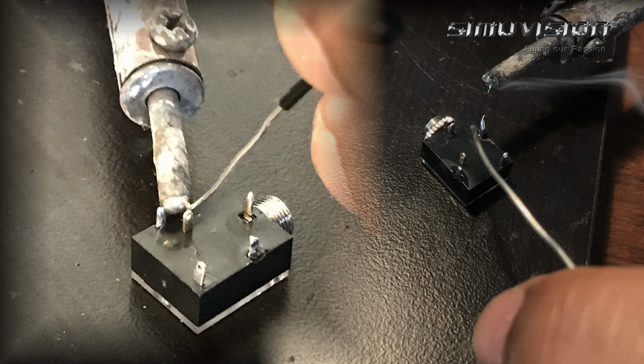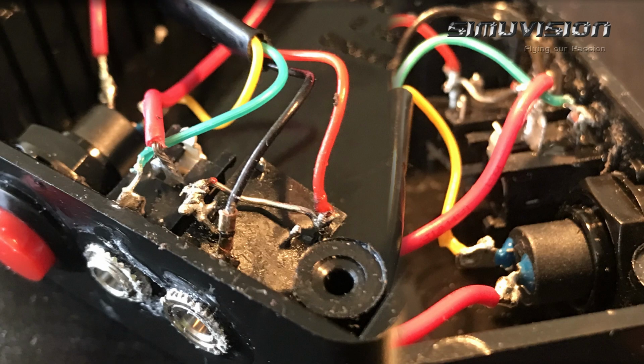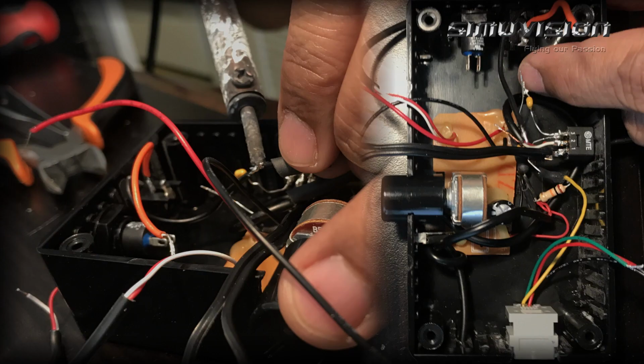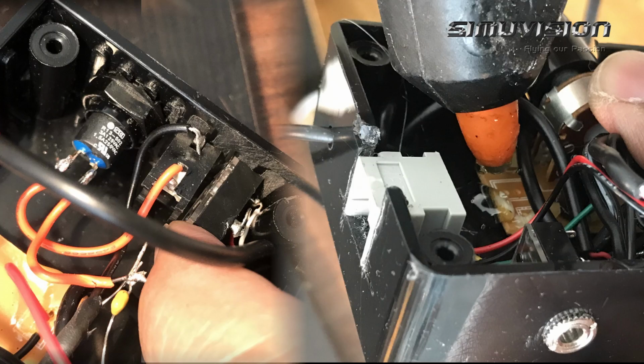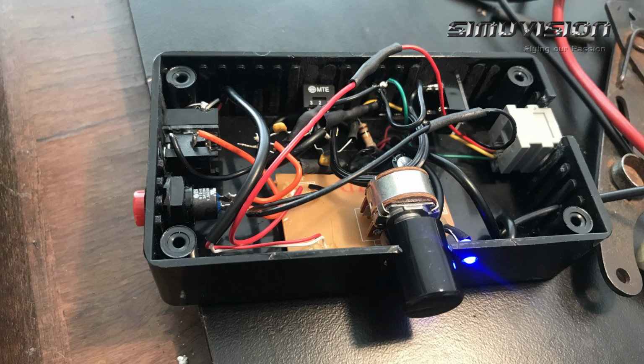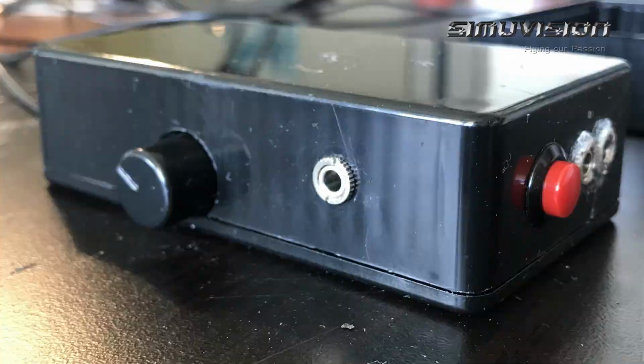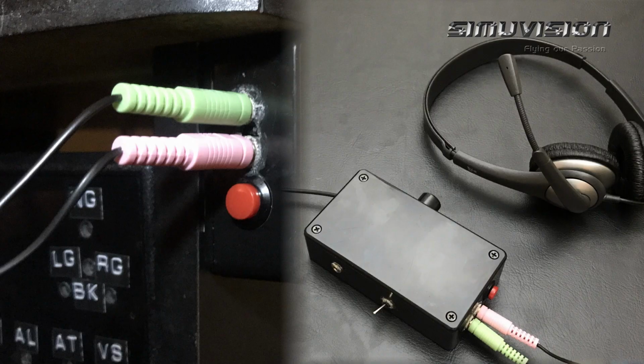Make sure that you're putting a stereo for the headphone set, and then you are putting the mono for the microphone. And this is the preamp circuit we put for the microphone. And in the stereo one, make sure that you are shorting both the left and right point. Now we glued the entire thing up and fitted it right in the box, and the boxes were ready to serve.